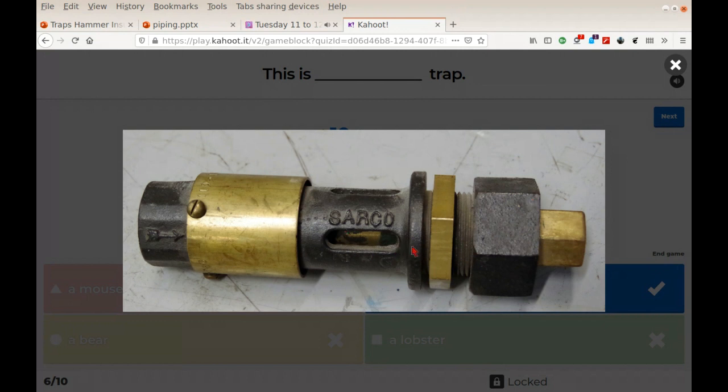It's really kind of old school, and I sort of wish that it wasn't in the textbook because it's been superseded by a type of trap called a balanced pressure trap. But one of the problems that they have is that they back up condensate. So if you're discharging condensate at 60 degrees Celsius, that means that the condensate's got to cool off for a really long time. And if you've got a really high pressure steam, your condensate saturation temperature might be, say, 150 degrees Celsius, and you got to wait for that condensate to cool off to 60 or maybe even 100. So it has certain applications and certain interesting uses, but that's a liquid expansion.